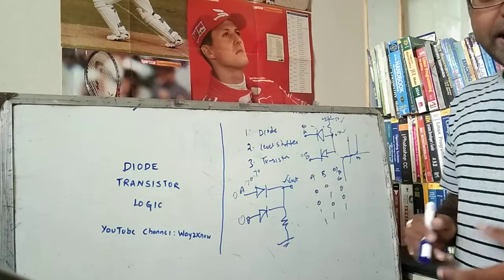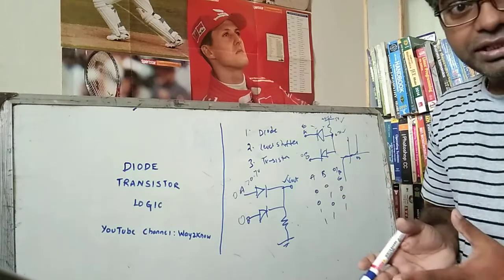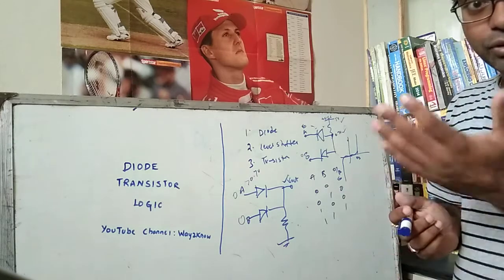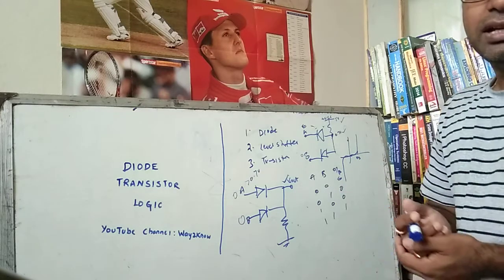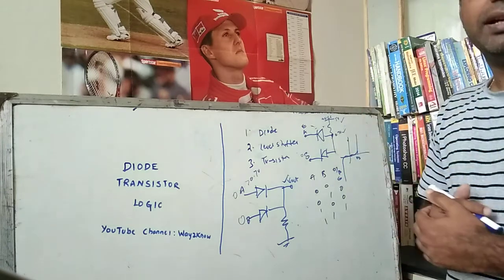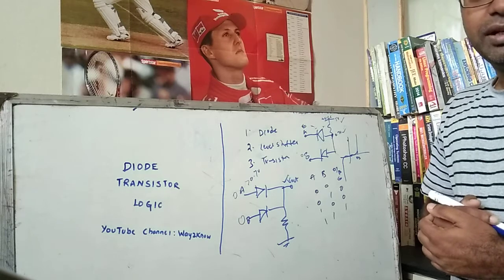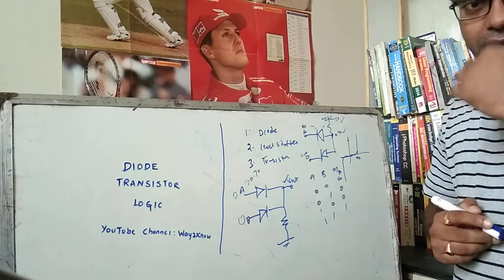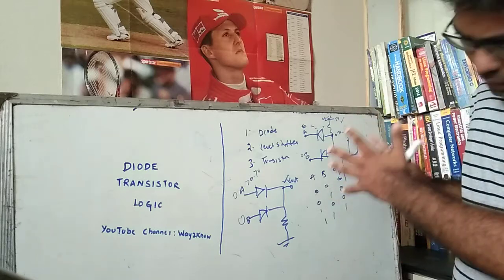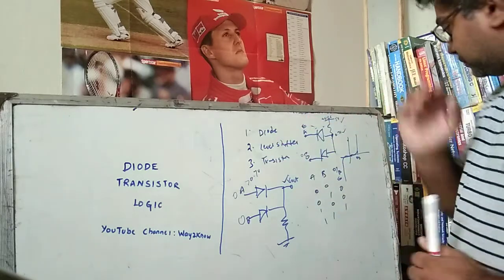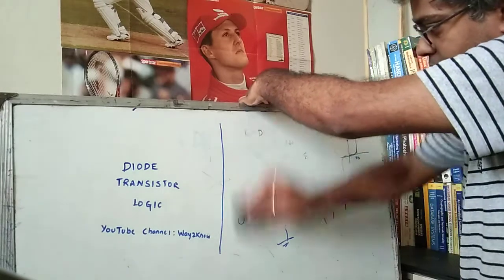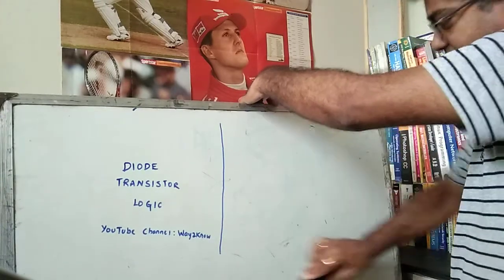And on the reverse bias side, if the voltage on the cathode side of the diode exceeds the breakdown voltage, again the diode breaks down and suddenly starts conducting a lot of current. So these characteristics are what you need to know initially. Now let us go to the second section.